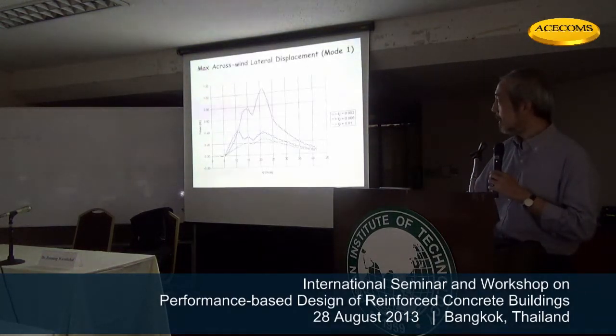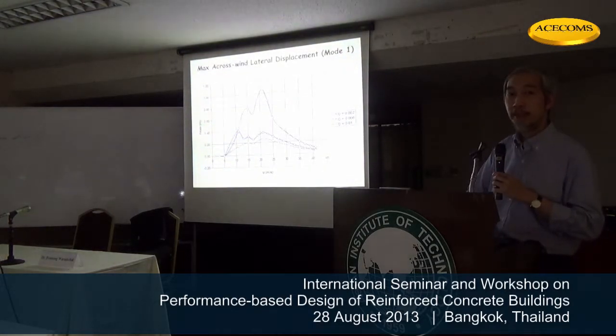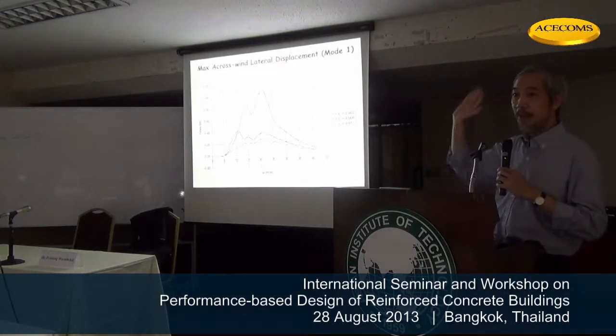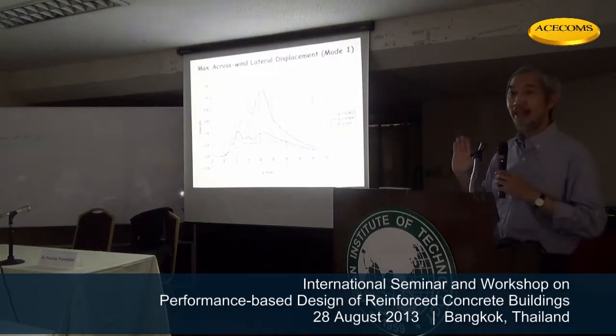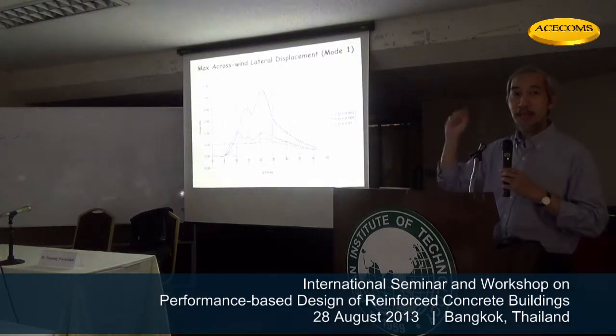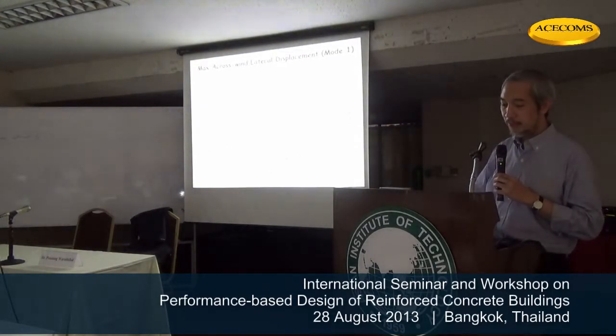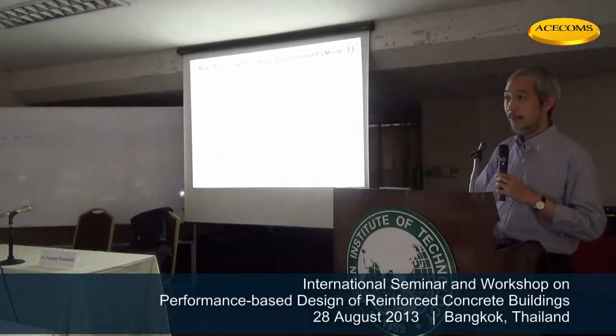And it says that if the damping is low, we may end up with a problem. Oscillation will be too large. The movement may be 0.6 meter, 1 meter amplitude. If you create bending fatigue in the column, in the stack, you're leading to some damage if it's sustained.